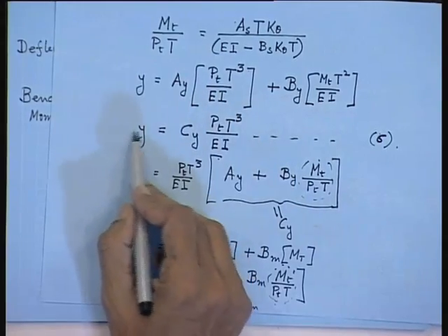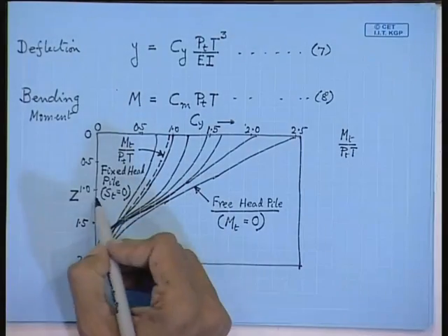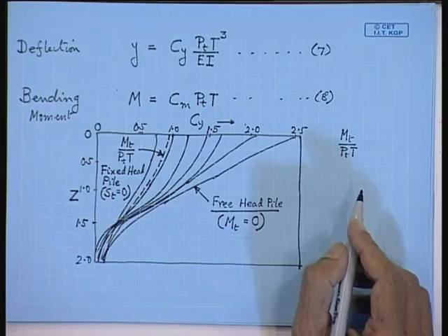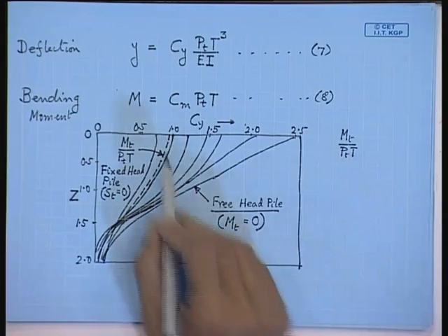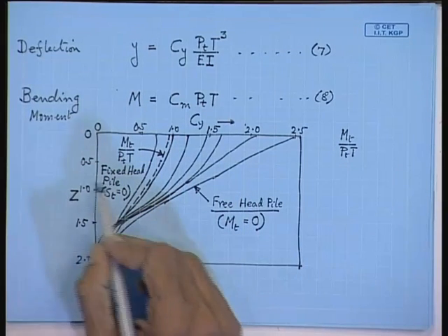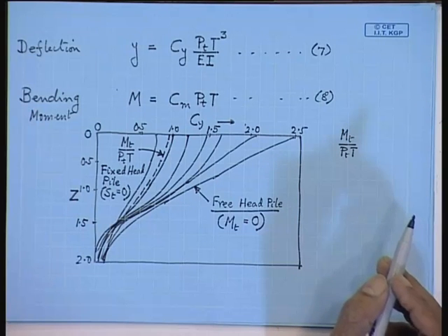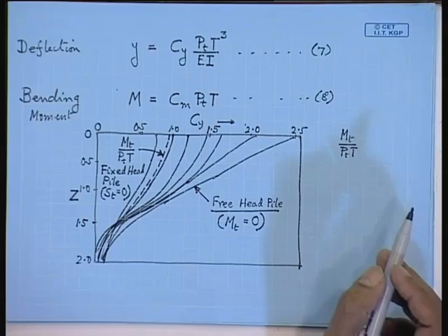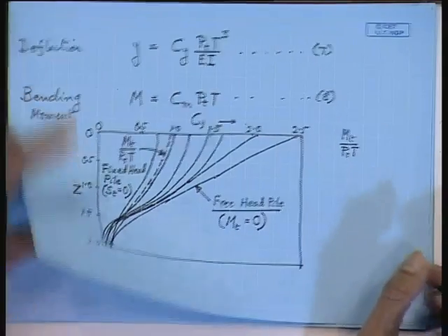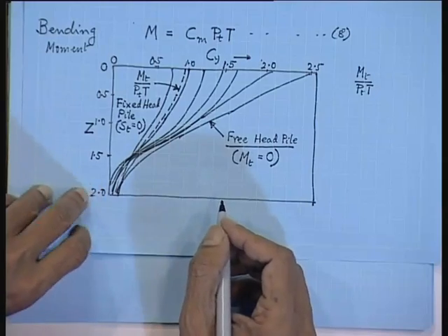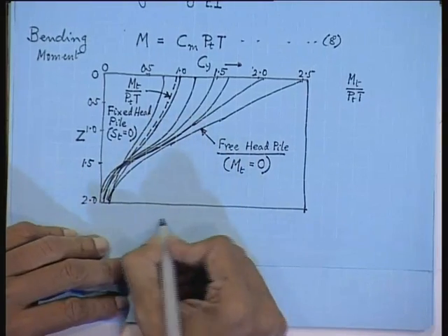So, immediately you can calculate Y at a particular value of Z. The Z is equal to XT. So, this is actually not giving in terms of X, this is giving in terms of Z, that is your non-dimensional coefficient. So, this we can find out the pile deflections. This is given in Reese and Matlock 1961.